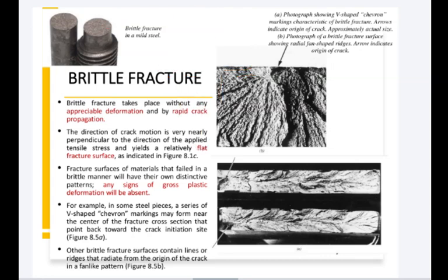We don't see the plastic deformation. And the pattern is what? You see here, these are the points where the fracture gets initiated, and then suddenly it propagates in a circular pattern, like you see, making a star. Let's say this is the point where the crack initiates, it propagates in this way. It makes a star-type structure. You will see some lines, right? This is where the cracks initiate, and then it propagates suddenly.